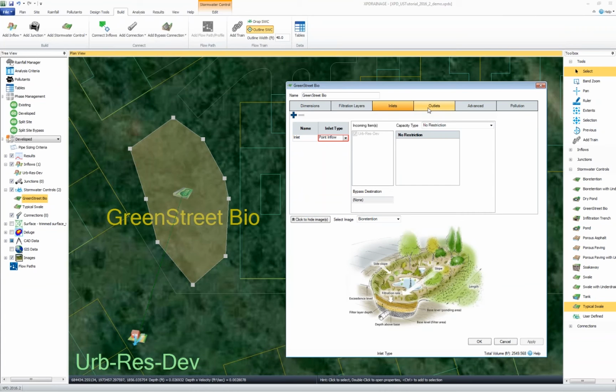Similarly, if you have, let's say, an inlet grate and you want to restrict the grate on top, that's there as well. You can restrict that inflow, and so on and so forth. We'll look at outlets. That's one of those main pillars of sizing and designing our site. How big storage-wise do we need? But also, what's the outlet configuration? It's pretty easy and robust to either input things manually or use one of the design tools.